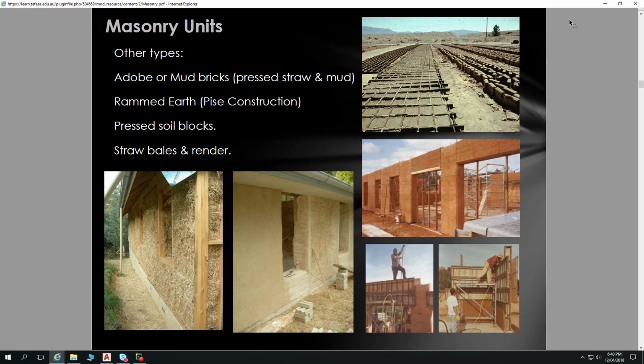So that technology doesn't have to be confined to just that arts and crafts kind of aesthetic. But rammed earth, definitely some really groovy stuff happening with rammed earth, except once again, the new requirements of the National Construction Code and the insulation for external walls is a problem for rammed earth, and so we don't see that happening so much anymore either.